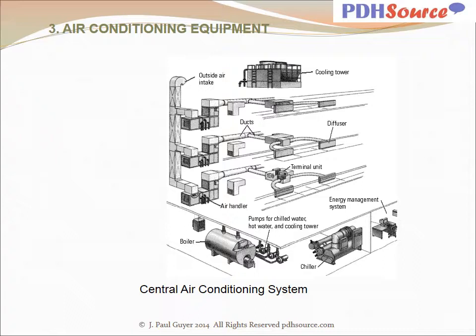Now also down in the basement or in the mechanical room is another piece of equipment called a boiler. And the boiler is either a hot water boiler or a steam boiler. And steam is certainly a common heating media, but in the typical commercial applications that we see, steam is not used that much because it's kind of high maintenance.